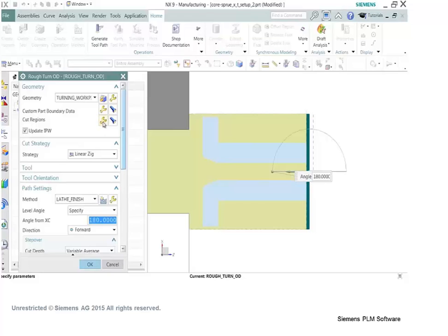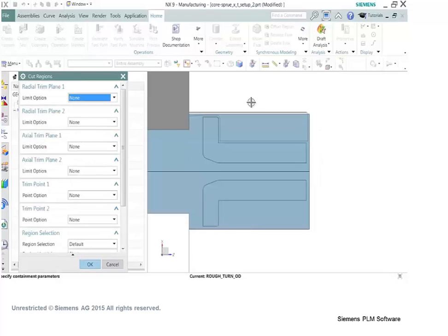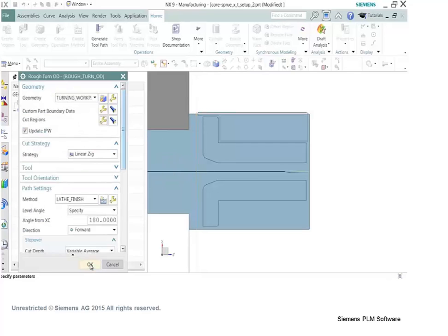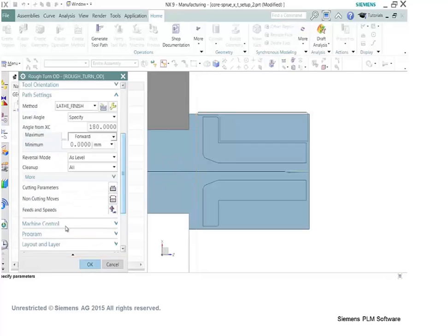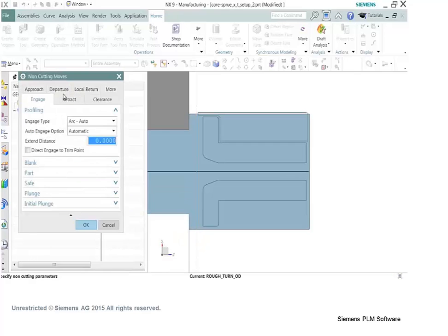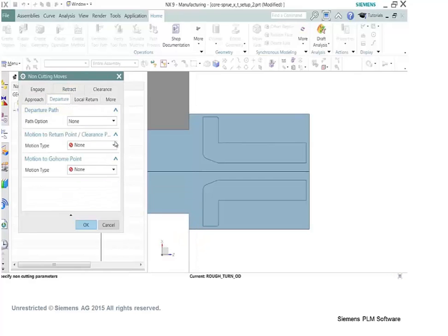If we look at that, look at the path that it already says it can cut. And of course, it's going back all the way to my chuck jaw because I didn't tell it the chuck jaw was a device component, something it should stay away from. But I can do this: I just clip the path off, and we're going to tell it we're going to stop out there at that distance.